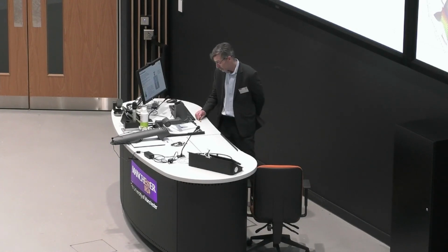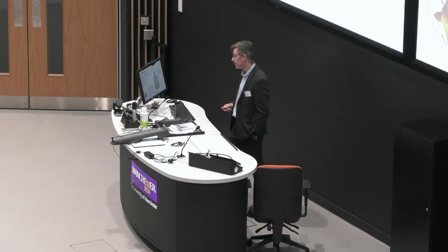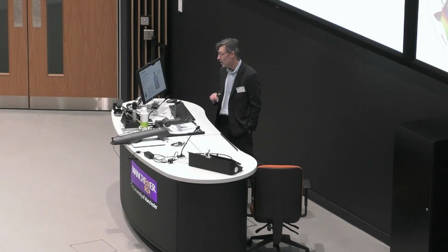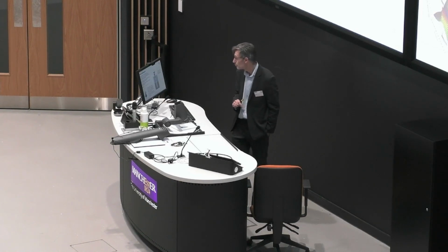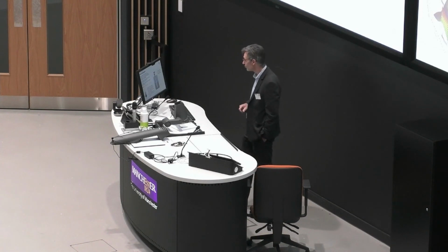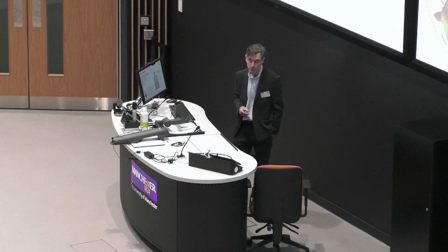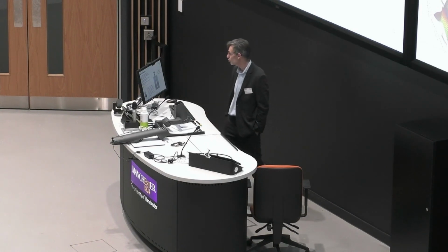Again, this issue has been addressed in the latest standard, and it recommends detailed analysis by computer modelling if you're concerned about anode location being too close. It's also suggested to apply a coating. Particularly during the initial period, if you can reduce the amount of current that is required, then you're able to develop a stable and protective calcareous deposit on the surface, which improves the long-term performance.